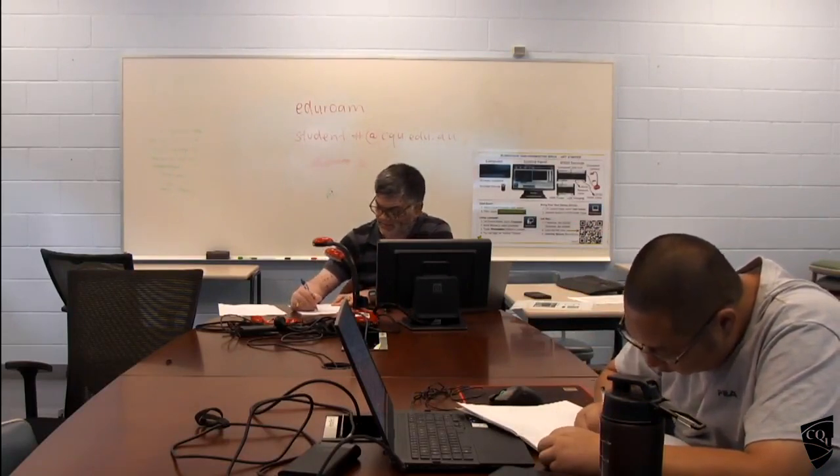If you have beams in four directions or three directions, the load will transfer to all supports. Here with two it's easier, but if you have four, the question is how much load will go where. So we use yield line theory of the failure.